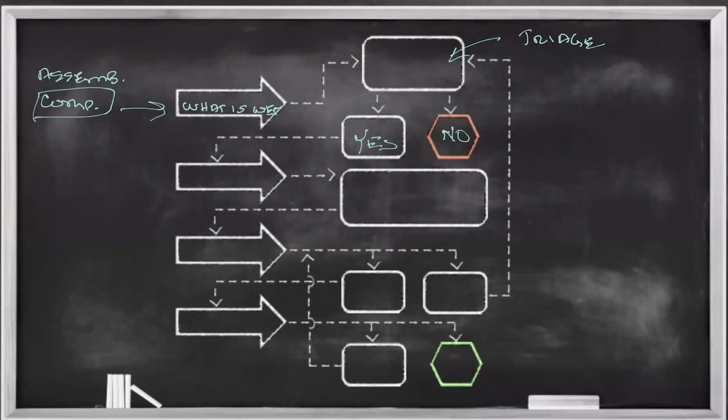Once we determine that something is indeed restorable, and that we do have restorability, the second question that we have to ask is how wet? Now, notice I haven't even established class of water yet, right? Because both of these inputs are really necessary to establishing that class. Where is my water? How deeply absorbed is it? Are we talking about just wet surfaces? Are those wet surfaces highly porous materials? Where does that water really exist within my structure? Documenting how wet means that I need numbers.